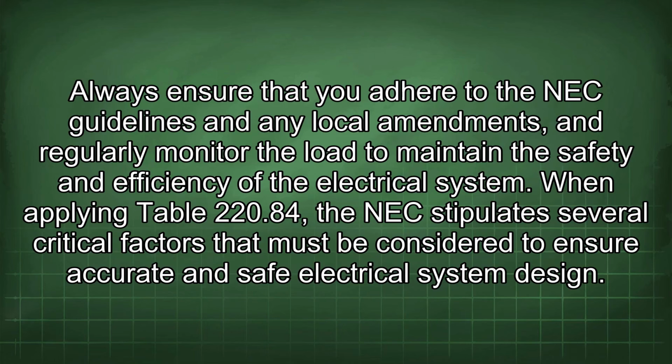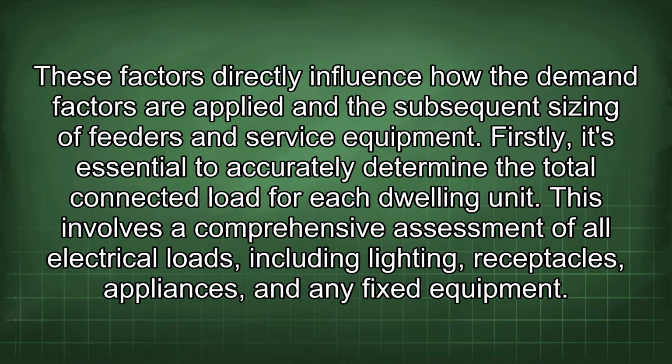When applying Table 220.84, the NEC stipulates several critical factors that must be considered to ensure accurate and safe electrical system design. These factors directly influence how the demand factors are applied and the subsequent sizing of feeders and service equipment. Firstly, it's essential to accurately determine the total connected load for each dwelling unit.